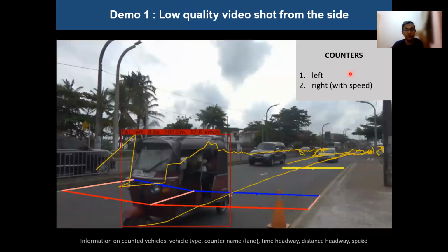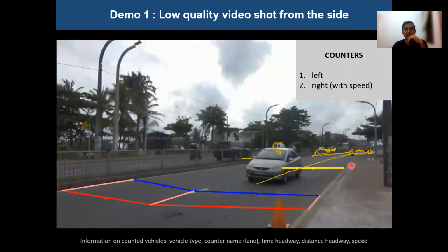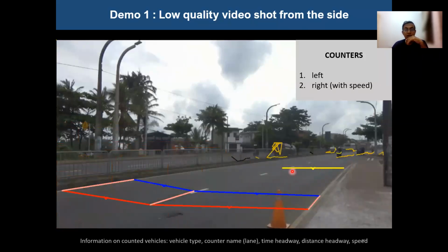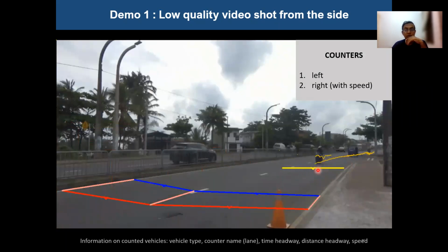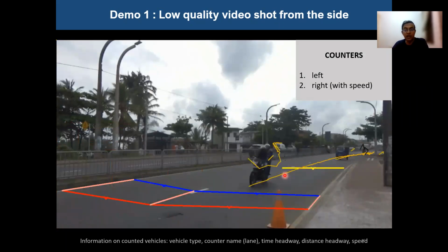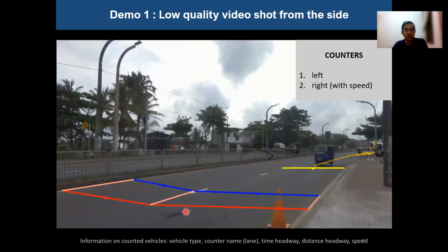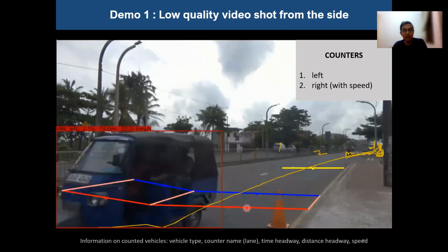So this is a video of that traffic analysis tool. You can see these lines. From here to here is about 10 meters. So you measure the speed of the vehicle. And this is tracking. You can see these lines, vehicle tracking, and it exits over here. You count it, okay? So you measure the velocity here and you count as it exits from here.